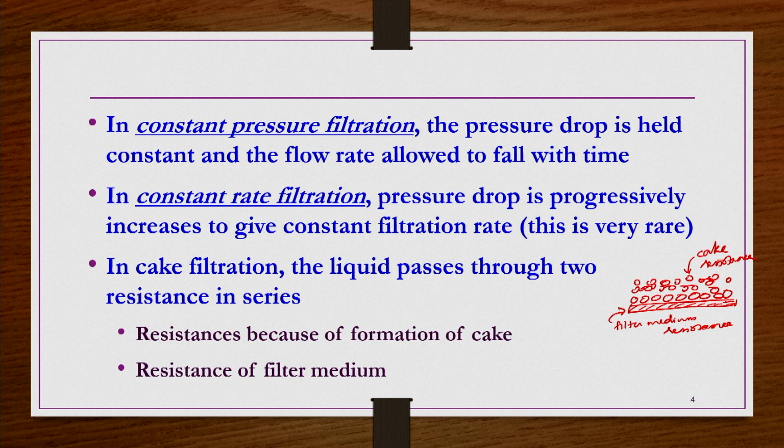So, one should have information about what this cake resistance is and what this filter medium resistance is. We need some information, or we should develop an equation, so that by using some experimental information we can calculate these resistances for a given situation where cake filtration is taking place.